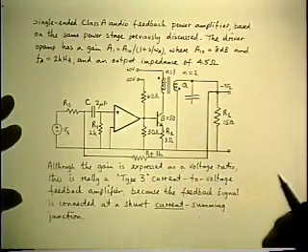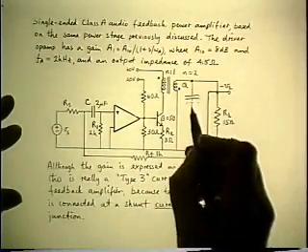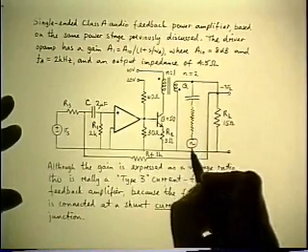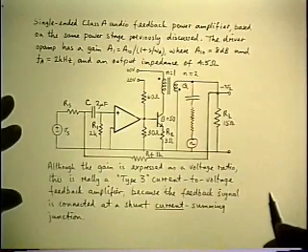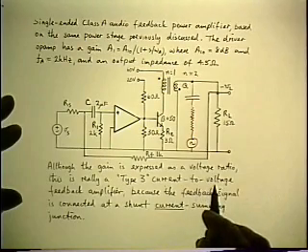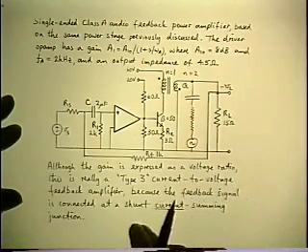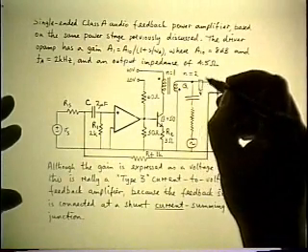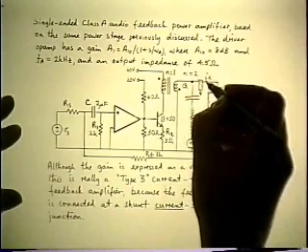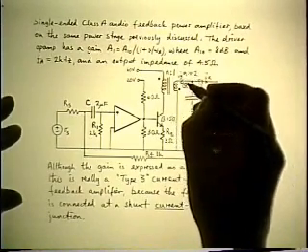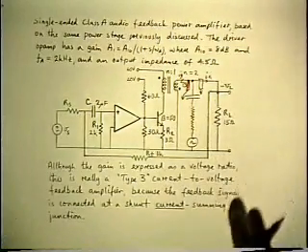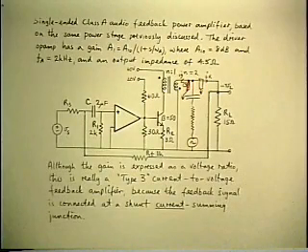Well, most of our signal sources are actually voltage sources, and so all you have to do is put a huge resistance in there and drive it from your voltage source. Then the measurement that you're going to use is a ratio of IY to IX. So you use two clip-on AC current probes, IX and IY, another one over here.